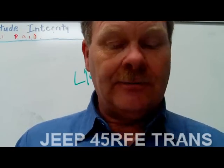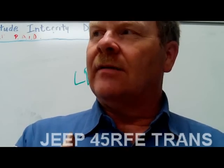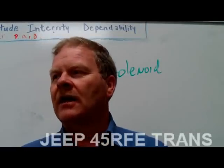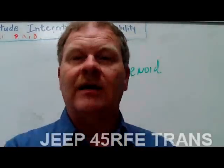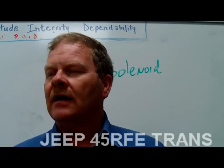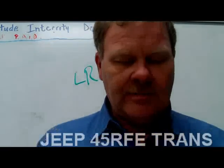So, see on these little Chevrolet Impalas and all that, when you mash the brake and your stoplights come on, it isn't because the brakes are turning on the stoplights. The body computer saw you mash the brake and it turns on the stoplights. So there's all that stuff in between. And it also sends the signals over here so you can take it out of gear and all that. So keep all that in mind.